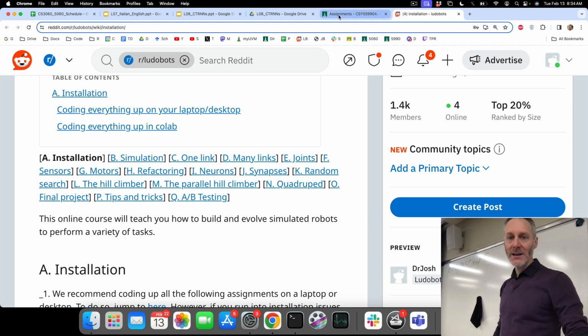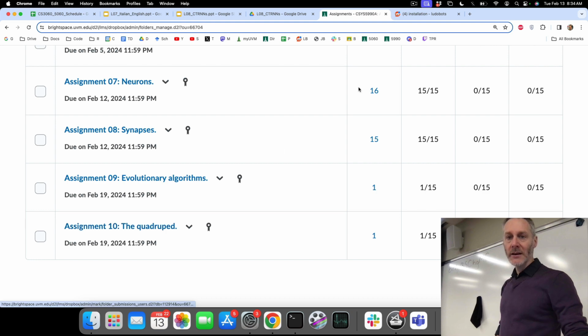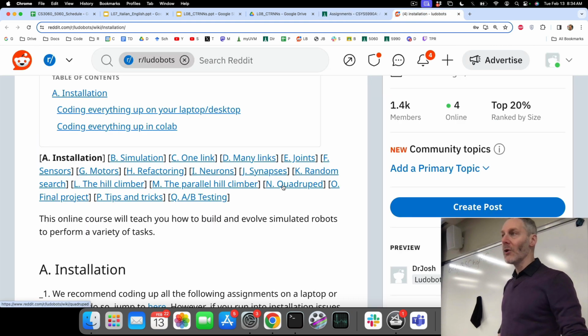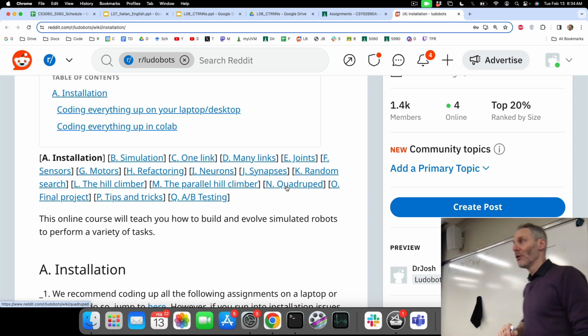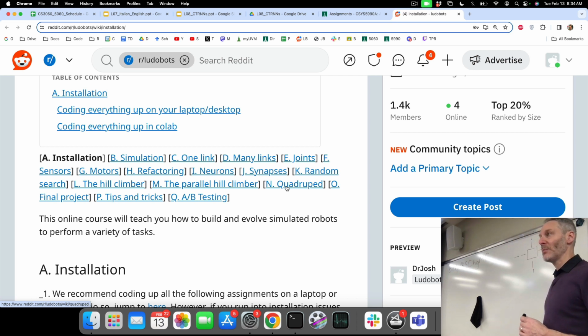That's assignment 9. Assignment 10, you're going to be throwing away this minimal 3-link 2-joint robot that you've been working with so far, and instead switch to a 9-link 8-joint robot that's got a main body, 4 upper legs, and 4 lower legs. For pretty much anything you're going to be creating in the PyBullet physics engine, whenever you have n links, in this case 9 links, you always have 8 joints, n-1 joints, right? Joints connect pairs of links together.